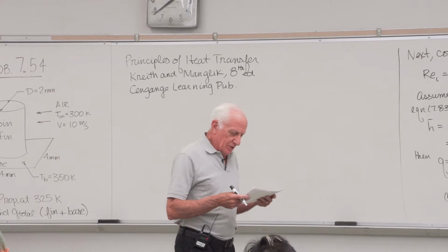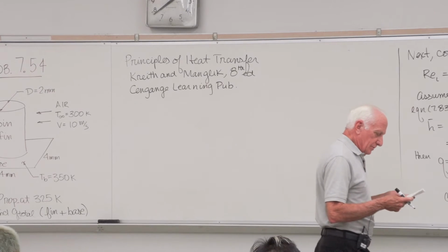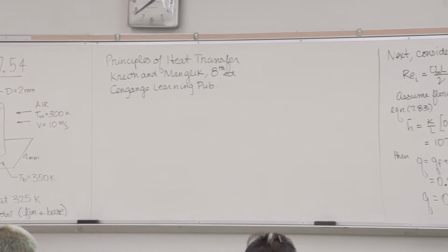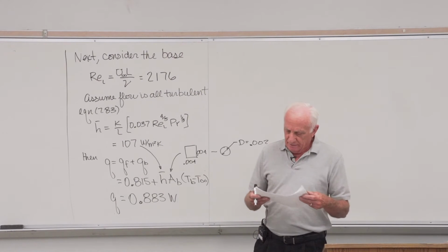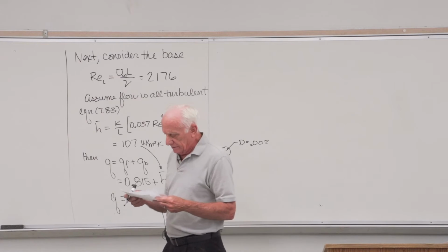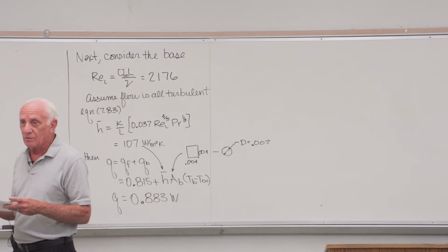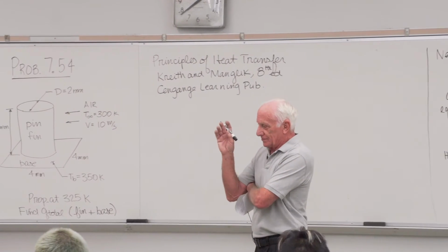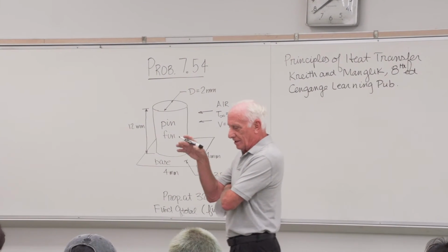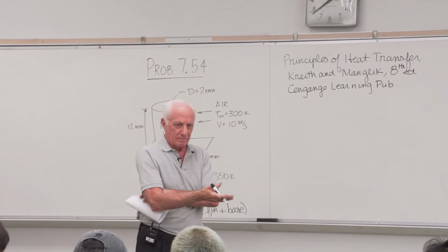Assume that the vibration of the engine and chassis induce the transition from laminar to turbulent flow so near the leading edge that for all practical purposes, the boundary layer is turbulent over the entire surface. Okay, major hint. He says to you, assume turbulent flow over the crankcase, the sides and the bottom.